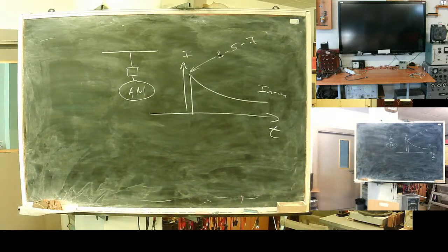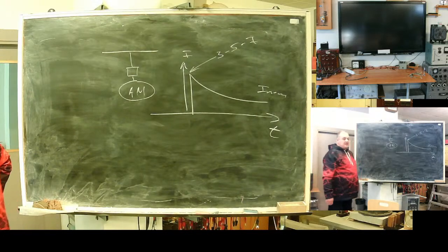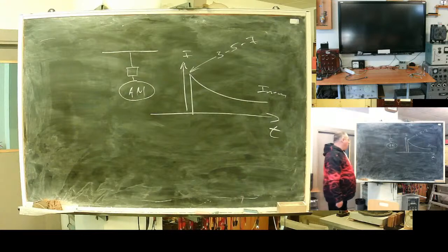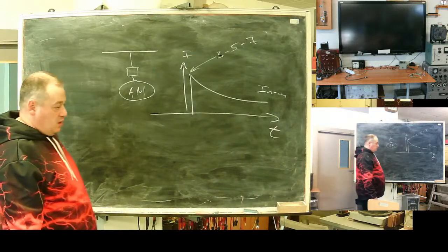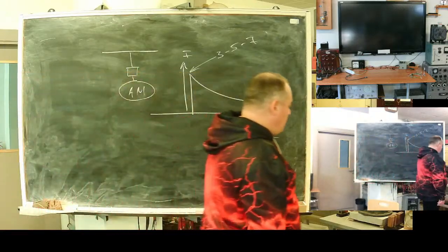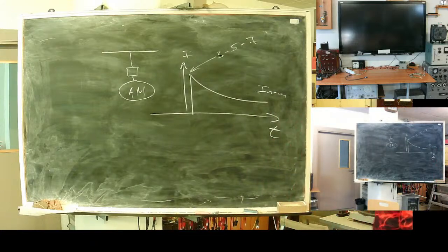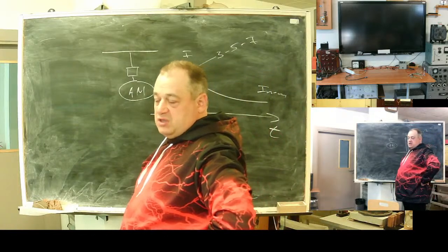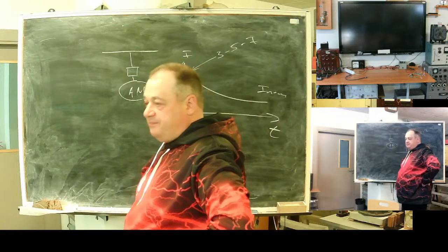Starting torque. What should we think? Actually, we need a kind of protection reflecting the thermal capability of this motor. It should allow high current for a short time, but it should disconnect the machine in case the starting regime is prolonged. It takes too long to start.